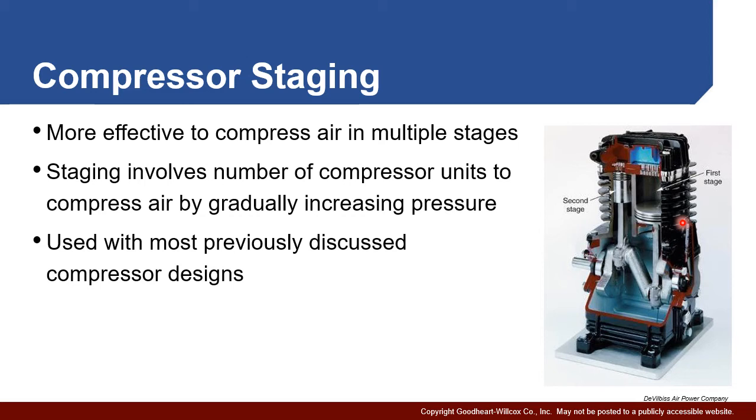One last thing about it, this is an example of a two-stage compressor, but keep in mind, if you want to go to higher and higher pressures, one of the best ways to do that is to use more and more stages. So you can have 3-stage and 4-stage compressors that keep bringing up the pressure incrementally.